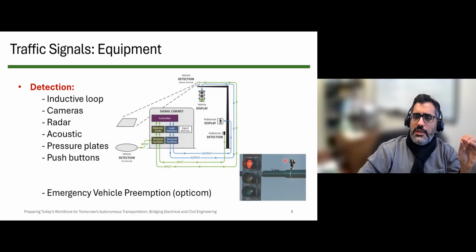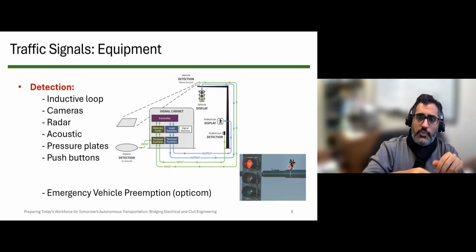It either works with the lights or with the sound. So those infrared lights that are received from the emergency vehicles, like an ambulance or a fire truck, will let the controller know that an emergency vehicle is coming that way. They will break the phasing scheme and assign the right of way immediately to the direction with an emergency vehicle.